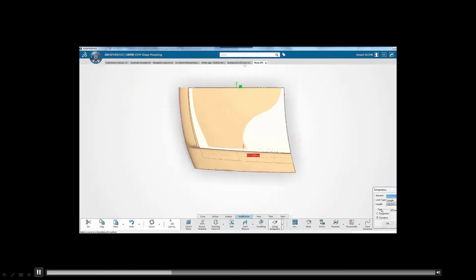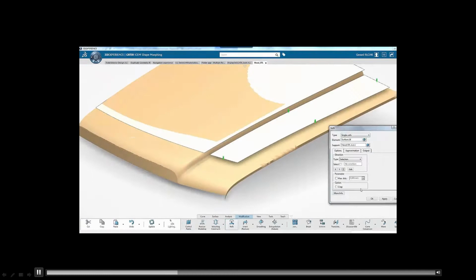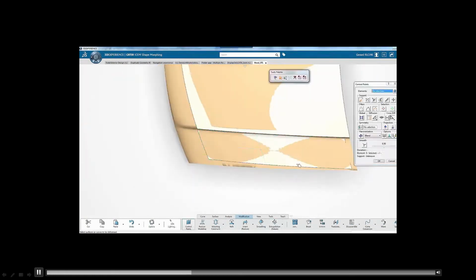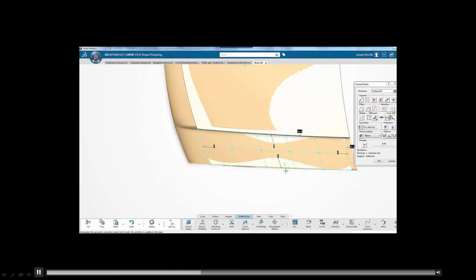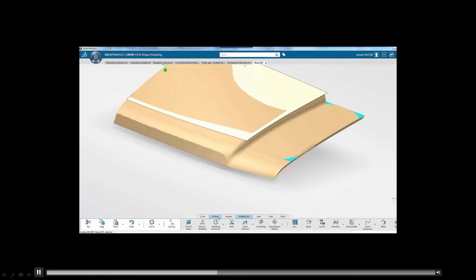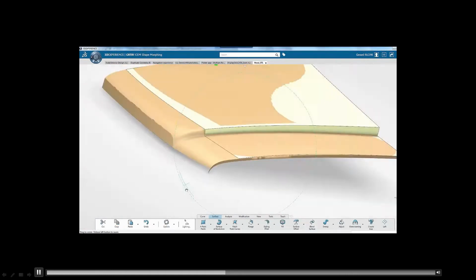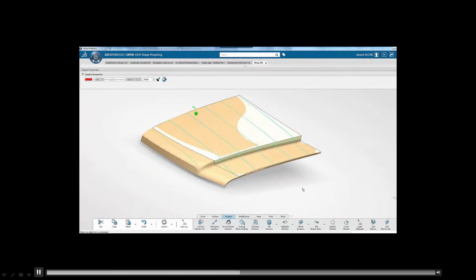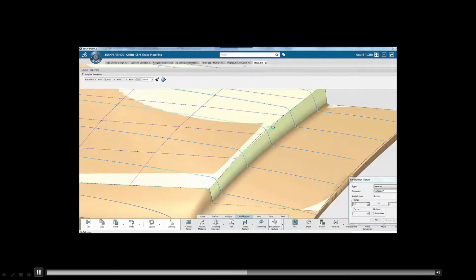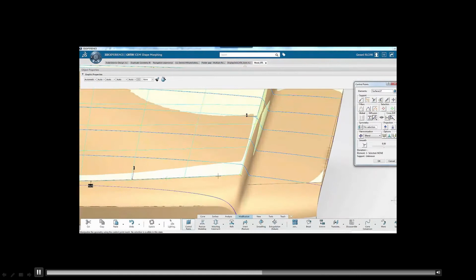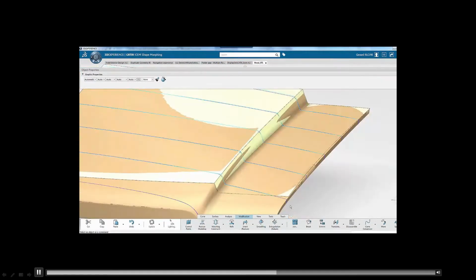Now we're going to accelerate it towards the outboard. Do the same thing for this outside portion. We project the surface on, go into our control point manipulation, add some diffusion laws, and fit the scan as well as we can with the exaggerated view. Now we create a blend in between those two. Put some section cuts. Of course, that blend is going to update as we change the edges of this explicitly created patch. The blend in between is associative.